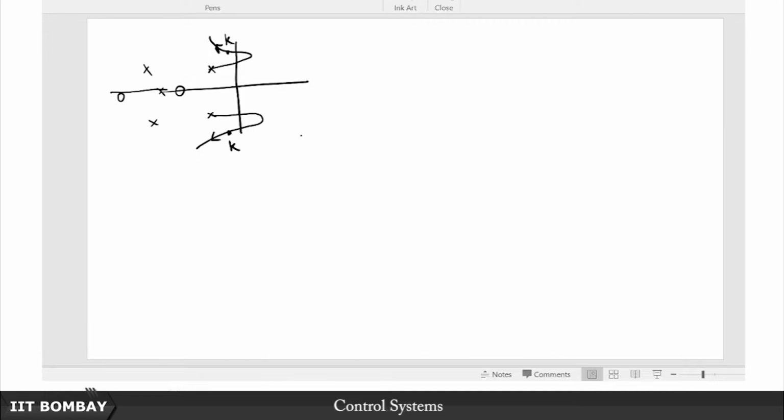Now look, here in order to explain this, I have resorted to this root locus, and from this root locus you can clearly see that this situation is not totally unexpected, right. You can have a root locus branch which goes from the LHP to the RHP and then comes back again to the LHP, yeah. So there are two crossovers here. Now this would, in the case of Bode plot, translate to multiple crossover frequencies, yeah.